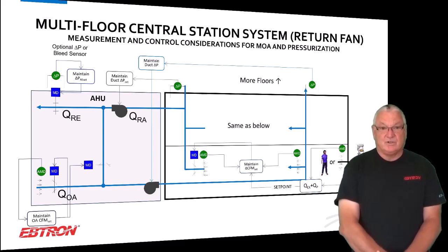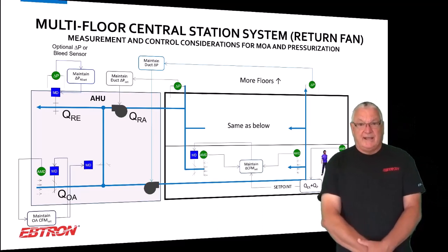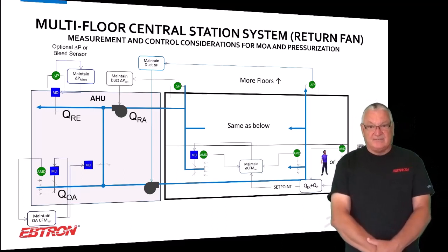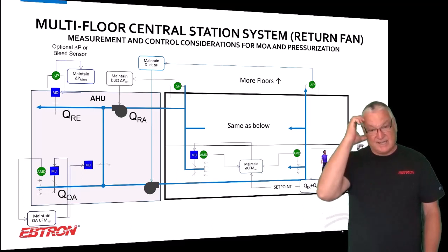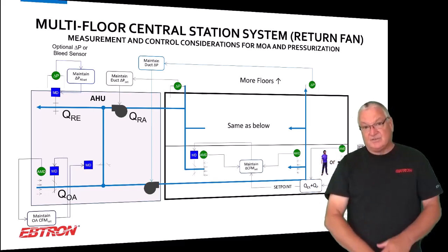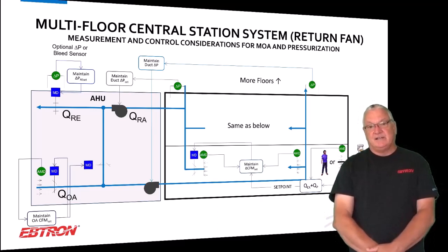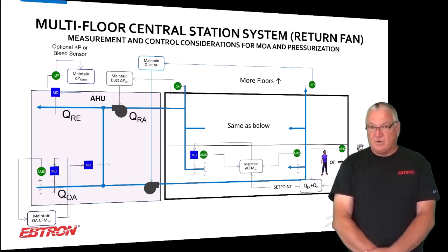And what we tell folks all the time is, look, you've got to get your outside air under control. No question about that. But you also have to get your floor pressure under control. That means you need to look at differential flow control on the floor level. You might reset it to static pressure to handle seasonal changes in stack effect. You do not want to ever sum the VAV boxes to get the total supply. You really want to measure the supply flow there.